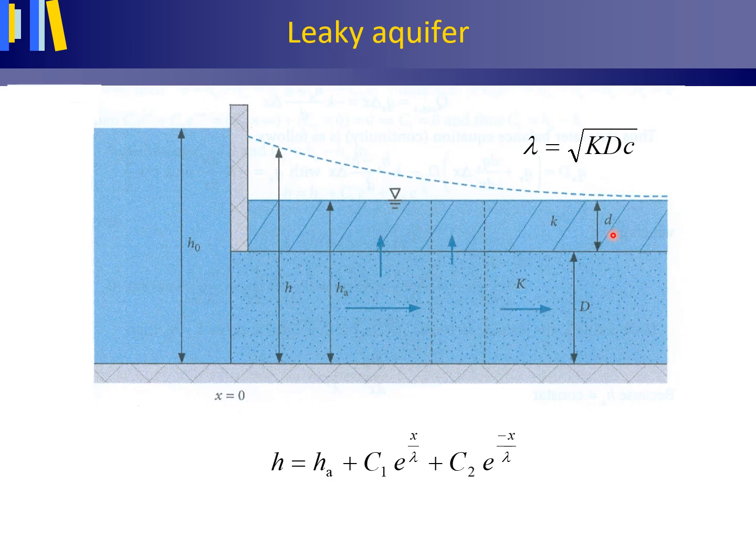C equals the thickness or depth of the homogeneously taken confining layer, small d, divided by the vertical hydraulic conductivity, small k, thus meters divided by meters per day, giving days.